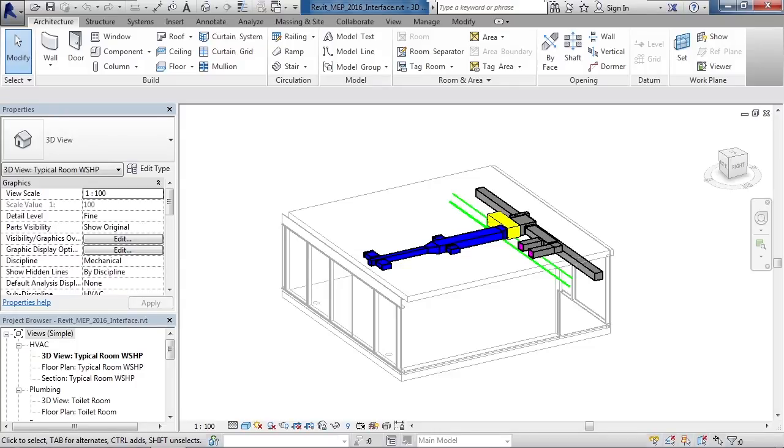In this lesson, we'll cover the Revit MEP interface. So when you open a project inside of Revit, you'll basically see a ribbon with a variety of tabs, and on those tabs will be panels containing various commands for Revit MEP. We'll start out by looking at the various tabs that you may have inside of your Revit version of MEP.